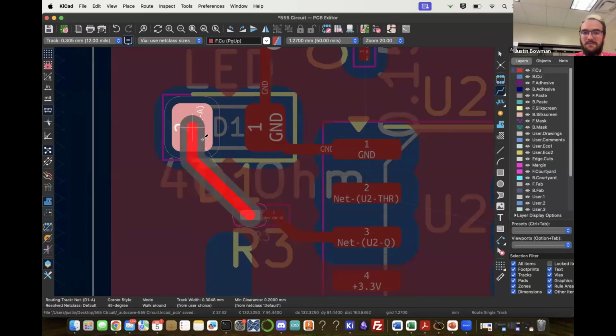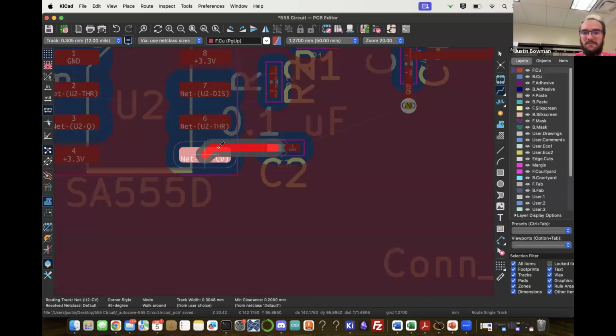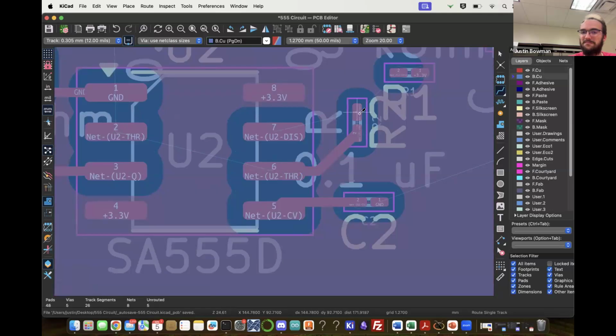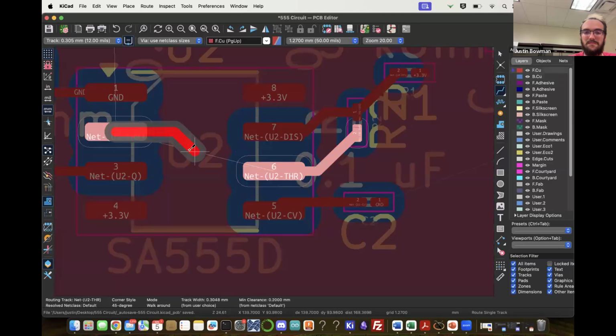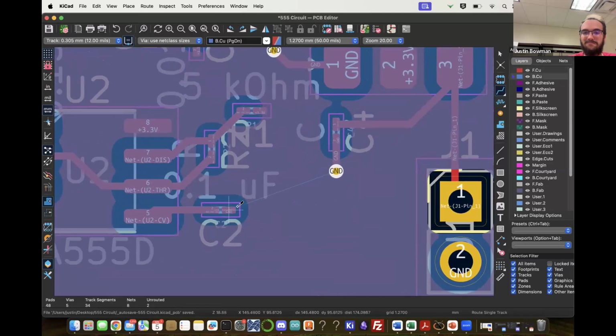I have tested it. I know robotics folks do that very often, they get the PCBs made there, and I have tried it a couple of times, it works. I know that they can drill the vias, and push come to shove, you just fill them up with solder. My thing is, if I'm going that route, I would make it a single-sided PCB.